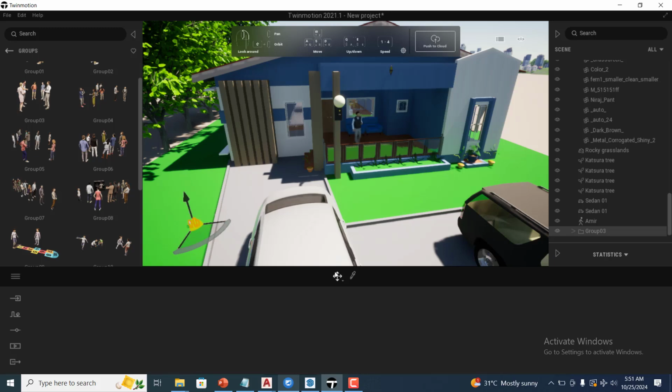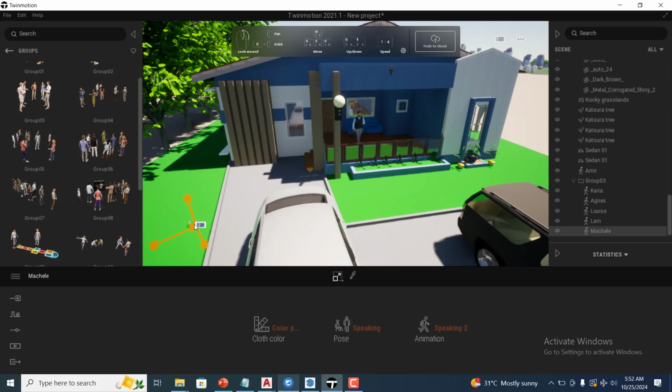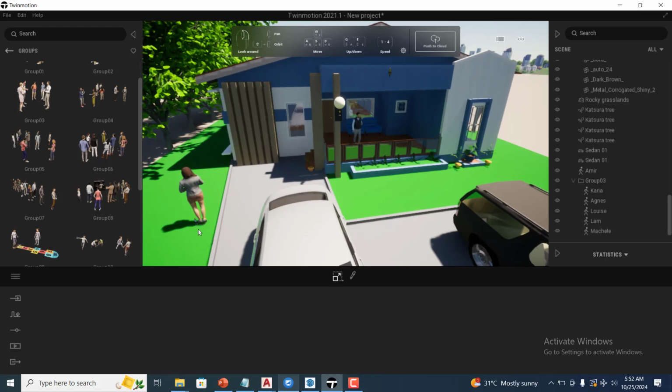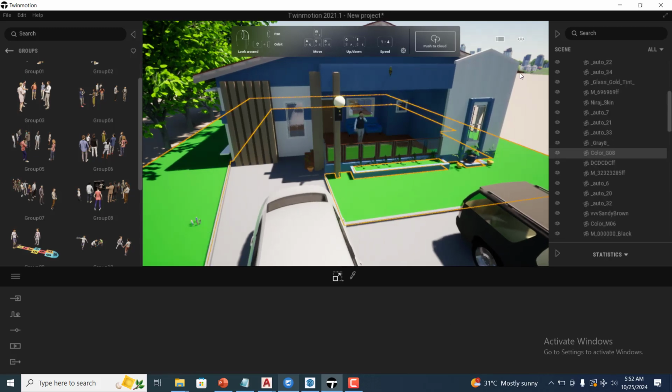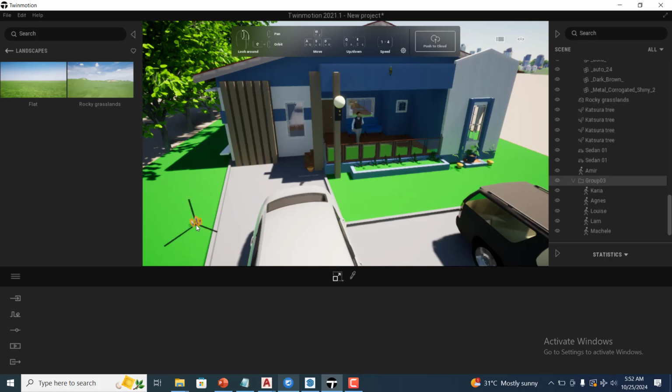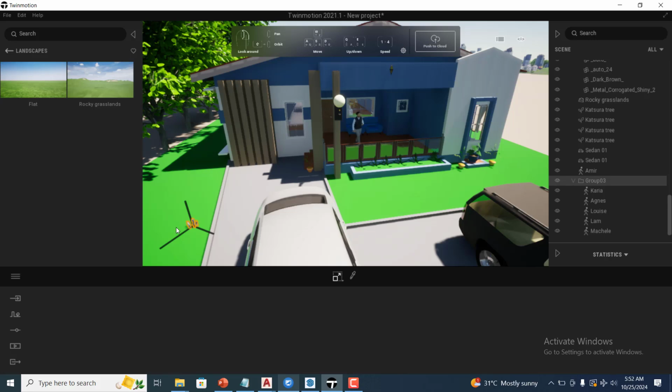All I need to do is move this, and then make sure you deselect. Then you press for us to scale. I think scale is 6 and 7. Scale is 7. You press 7, click on the character, and then you click on it again. Once it brings up this number for you, you type in what scale you want it to be. So let it be at 11. Oh, I think only one character was scaled. So you have to really do that manually for each of them.